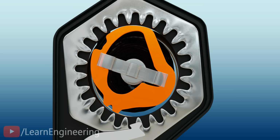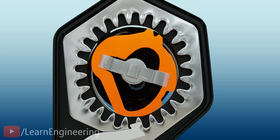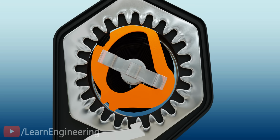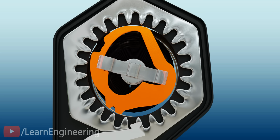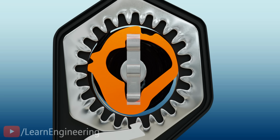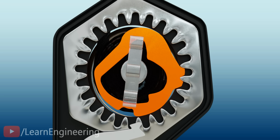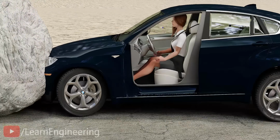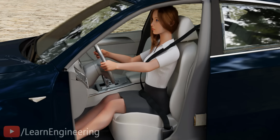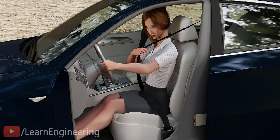If the central piece rotates slowly, the orange piece will be able to move with it. However, when the central piece rotates fast, the orange piece won't be able to catch up with it, resulting in an interesting lock, as shown. Let's watch the same animation in ultra-slow motion for better understanding. Obviously, the belt will lock when the passenger moves forward fast. Most importantly, this is an easy mechanism that everybody can test, which increases consumer confidence in seatbelt usage.